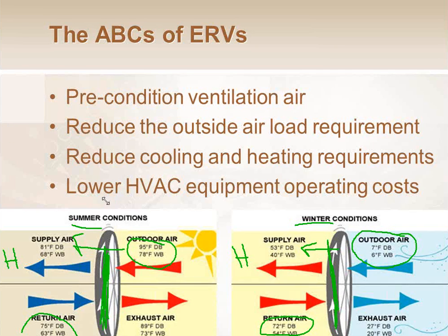All right, so in your case with the humid climate, even though most of the guys on this call are Midwest, you're in a humid climate, which is fine. Even in the Midwest, we have very high humid days for 3-4 months out of the year. So the type of ERVs that we're going to be using are going to be the ERV type, enthalpy recovery ventilators. We are not going to be using HRVs. And I'll explain the difference between those two in a minute.